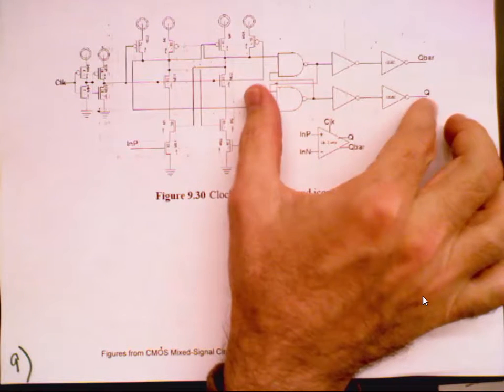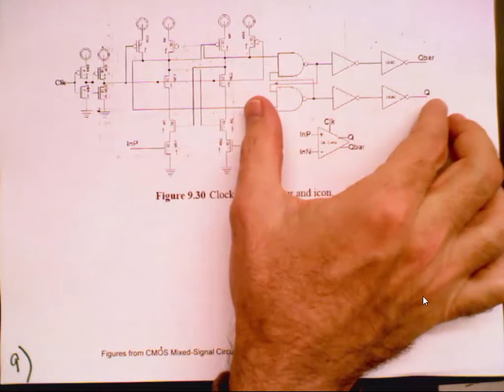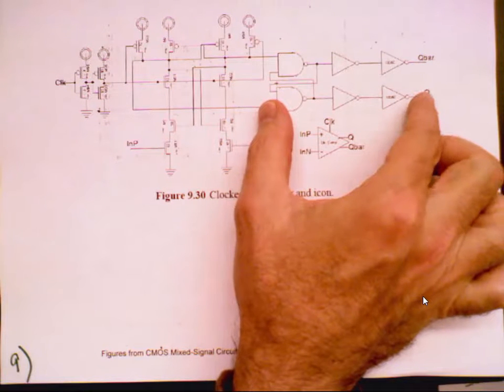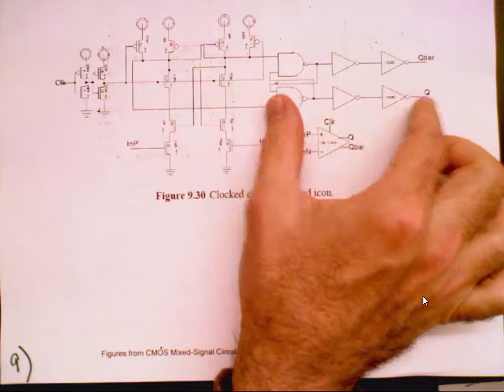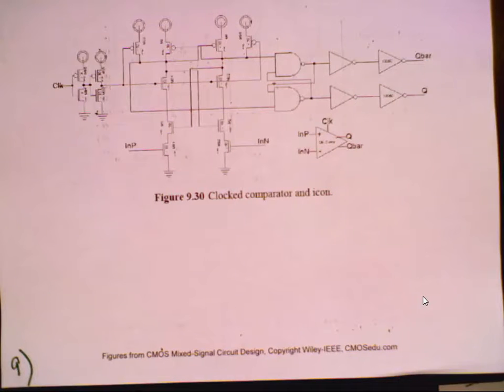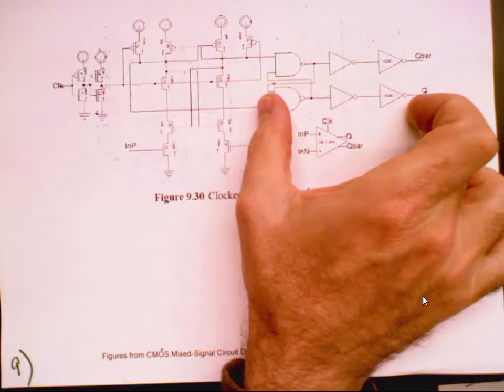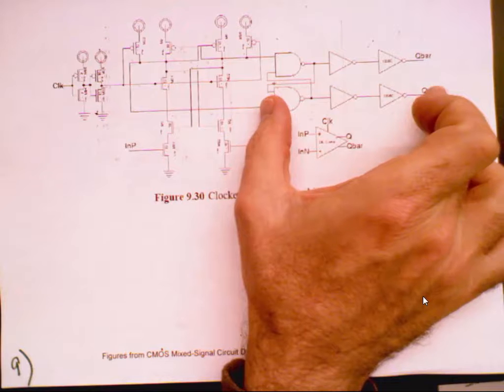You would like to get rid of this part, but you really need it to get real decisive square signals out. If you're using a 100 megahertz clock, then you'd have 1.25 nanoseconds worth of path delay, and I think that one gave you 800, 900 picoseconds of delay. Did anybody try it without these? No, I could have tried that without it.